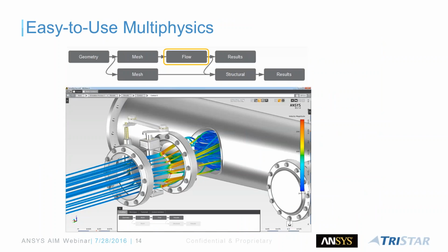And you can also have multi-physics templates or workflows where, here, you could see the first line is more of a fluid flow analysis where you may have to specify the inlet, the outlet, the walls, right? Give it the pressure, velocity, etc. And then for your output, you may be looking for mass flow rate, streamlines, path lines.